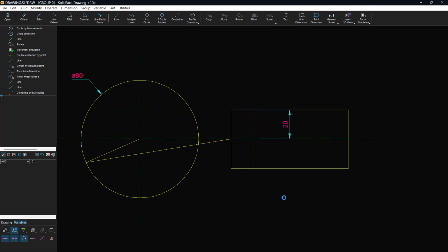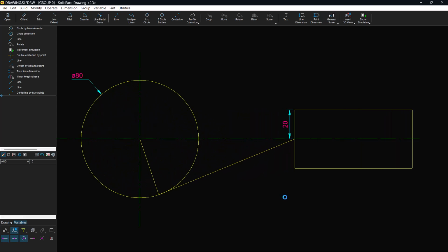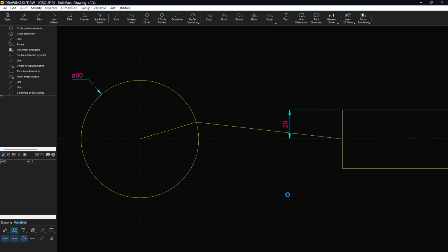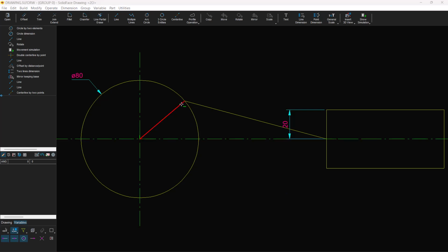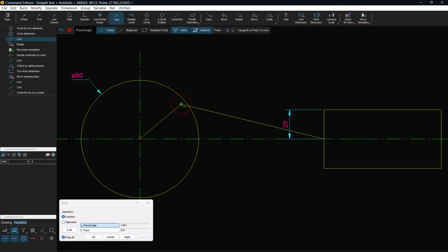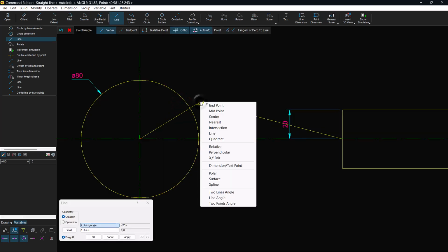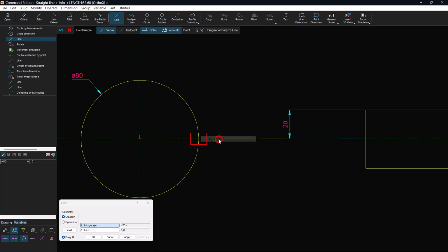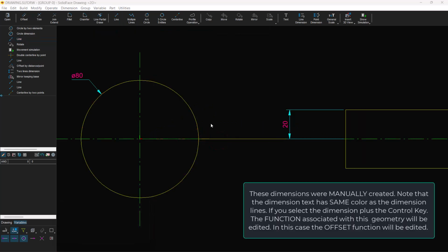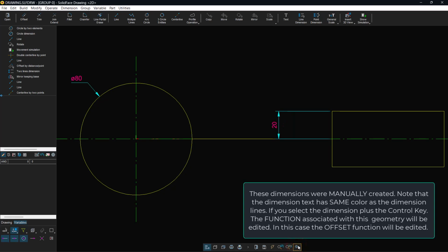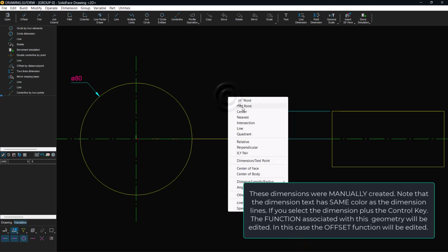Remember that the hand crank line was created at a point on the circle between 0 and 90 degrees. In that position, it was easier to show the simulation geometry construction. Now, once constructed, edit the hand crank line so its endpoint ends in the circle quadrant with angle 0. The straight line will be rotated from its horizontal position. The ang variable is at 0 degrees, and this is the maximum position of the piston displacement.